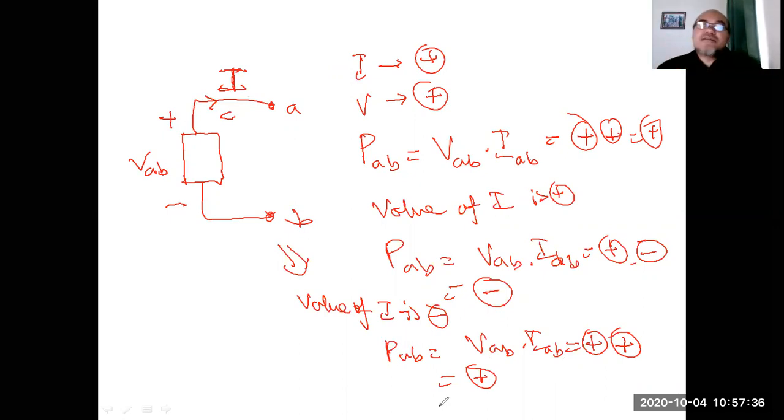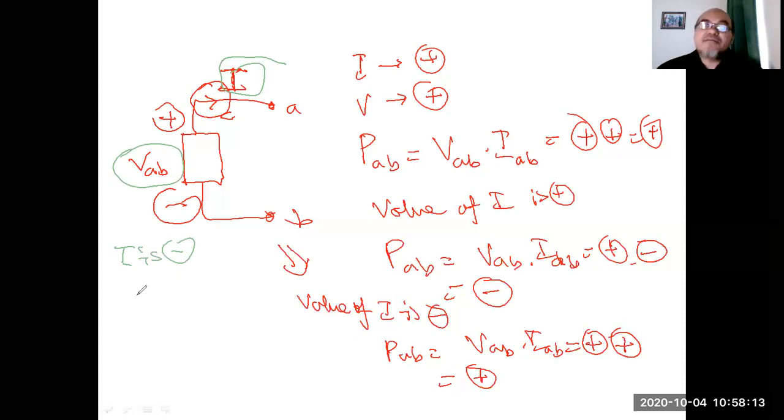Be careful with how you assign the current. In electrical circuit analysis, it depends on the arrow direction, or in the case of voltage, on how you assign positive and negative, as well as the value of I and the value of VAB itself. When the arrow flows to the right, however, if the value of I is actually negative, then you can redraw the circuit to make it simpler to understand.